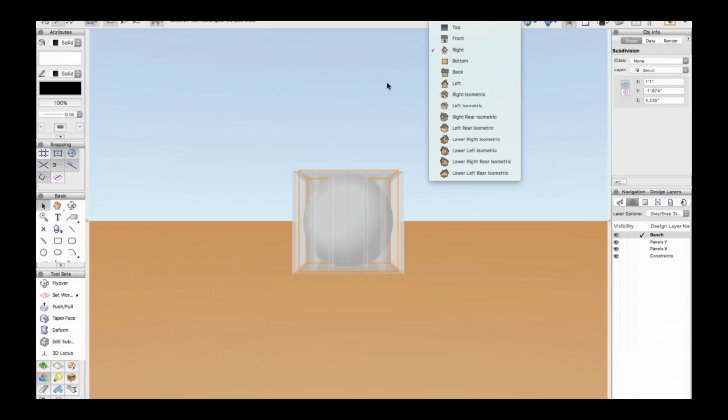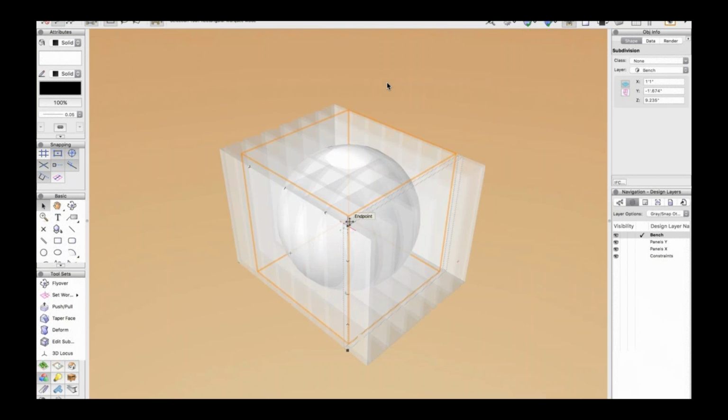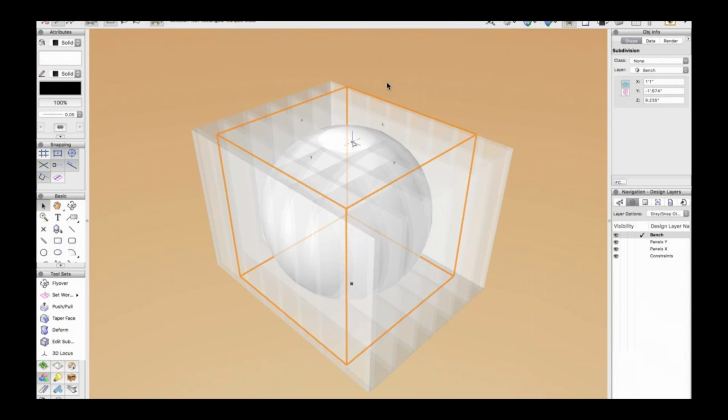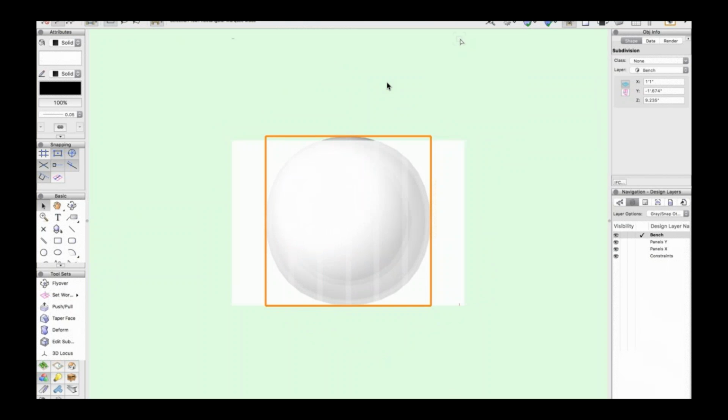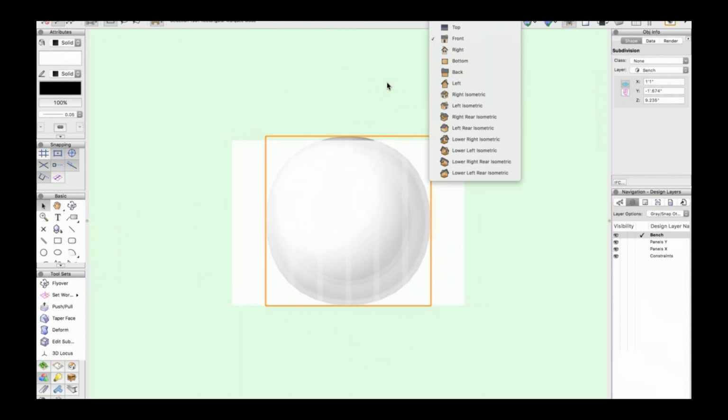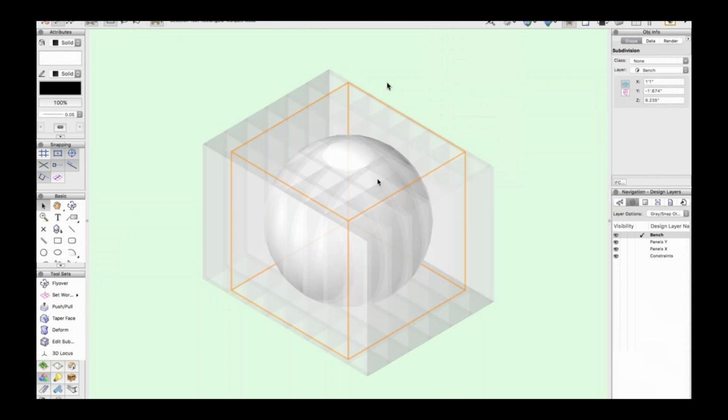So if you want your objects that are created through a 2D to 3D process to align with the objects you've created with subdivision, go ahead and check those in your front view and make sure everything's on orthogonal so that everything aligns nice and neat. So what you'll see now is that I've actually got my design layered.